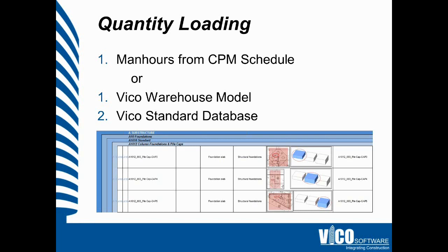The good news is, if you've implemented Vico Office or are looking to implement Vico Office, most of that work is done for you as part of the basic Vico Office workflow. So it's simply a matter of taking all that line item data, quantity data, and resource calculations, and assigning it to tasks to populate your schedule. In the absence of a model, we can use man-hours to resource load the schedule. It's a little bit less accurate, but it does give you some relative analytical comparisons from location to location.